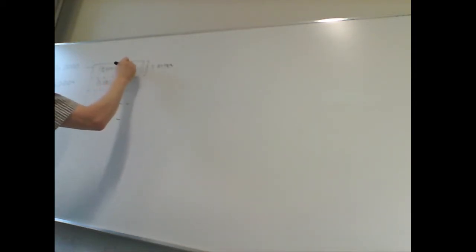And then I don't remember exactly, but basically all of these interrupts will take 4 bytes, and during those 4 bytes you must have code that jumps to a certain address. And here actually is a command, long jump to boot.